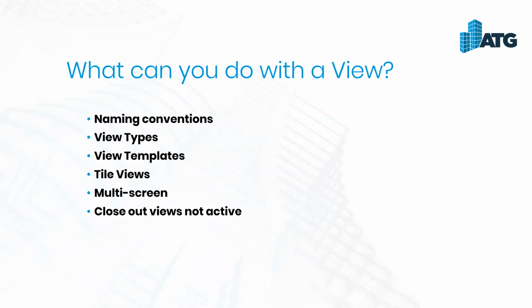So not only is it a great way to organize your views and make them more consistent, but obviously you can expand upon that and show your views specifically for that particular instance. If it is discipline specific, you're going to show those types of items within there. But you can also control where a view is going to be placed within the project browser by setting up the view templates as well, and getting those organized and plugged into each of the different types of views that you have in your project.